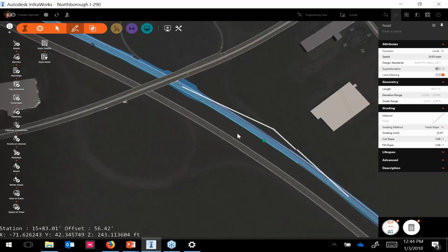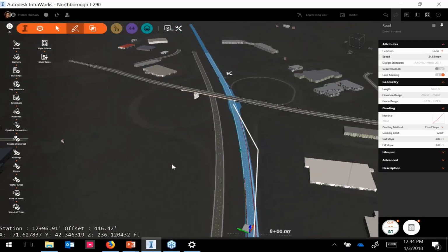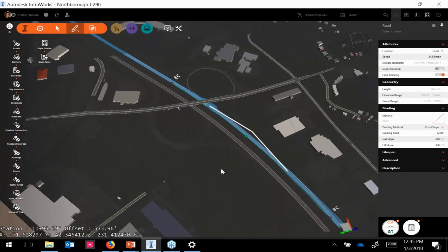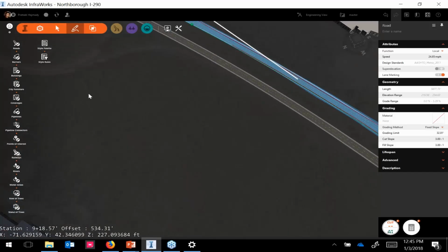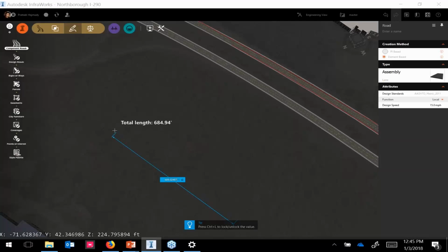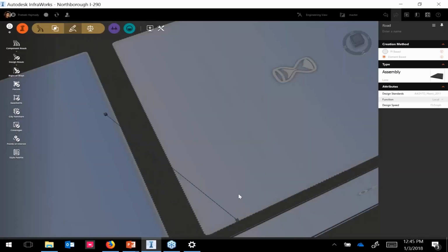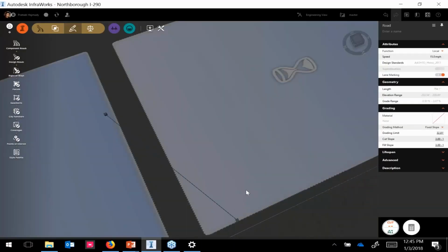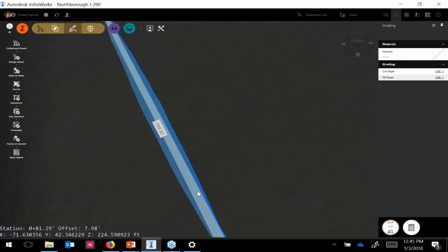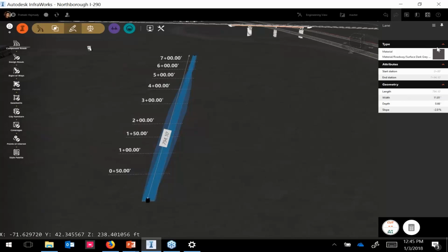Quickly talking through this, one of the other enhancements we've made was being able to set some of the parameters on a component road. So I'm going to take this clean region here and create a component-based road. It doesn't matter what type it is. Another enhancement you will see in this release is the capability of being able to set the depth for a lane component type.